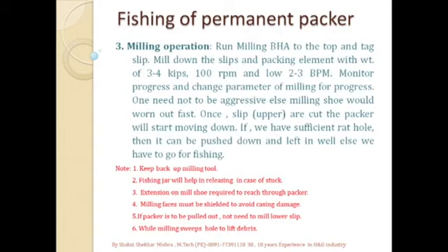So once the BHA is made up, we run to the top of the packer and we soft tag directly on the slips of the packer, the top slip. So we start with slow rotation and make the shoe touch the slip.